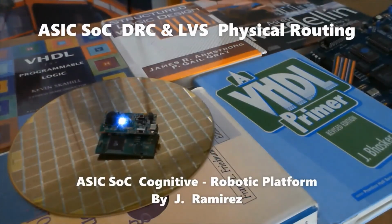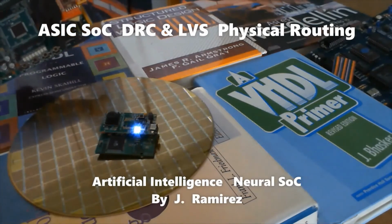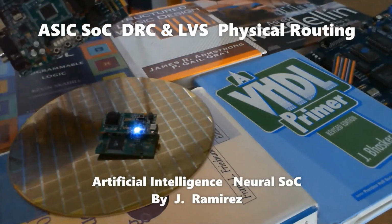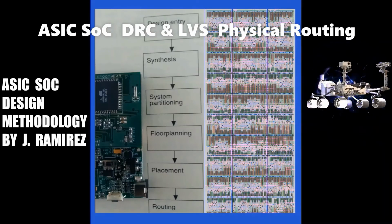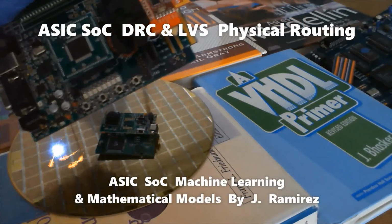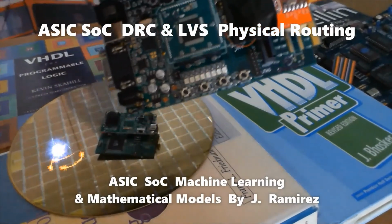I performed two major checks of the ASIC implementation illustrated in this video. They were performed before fabrication. The first check is the design rule check, DRC, to ensure that nothing has gone wrong in the process of assembling the logic cells and routing.